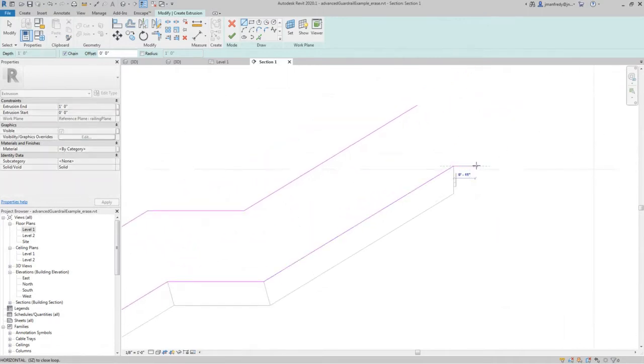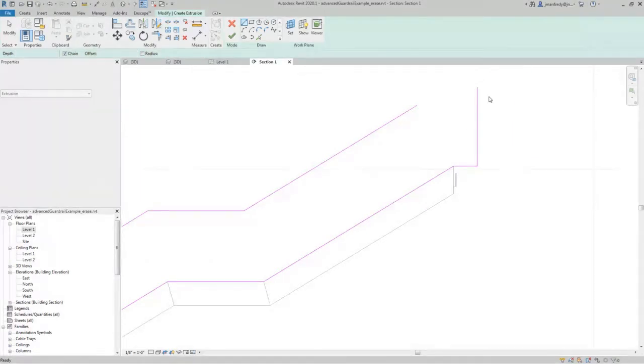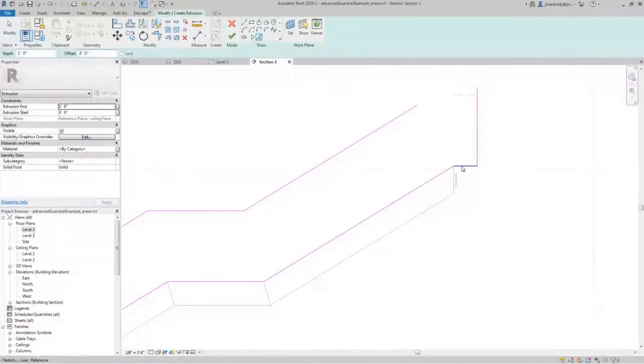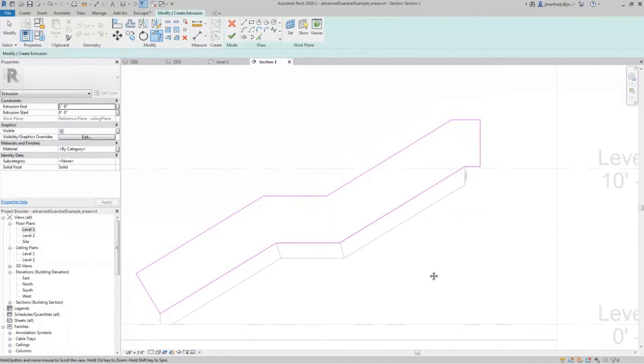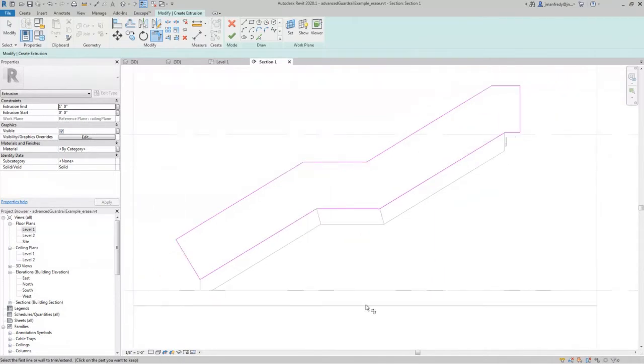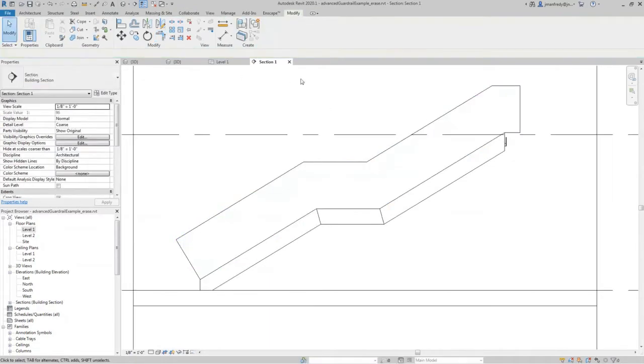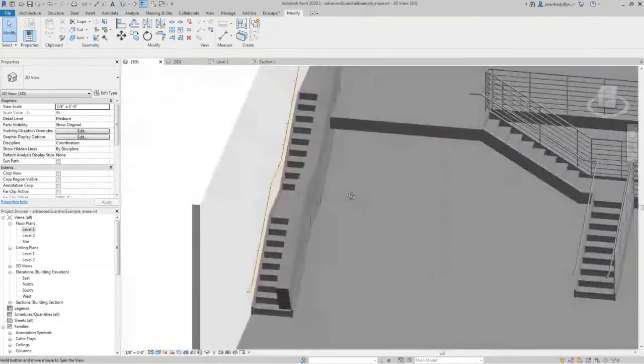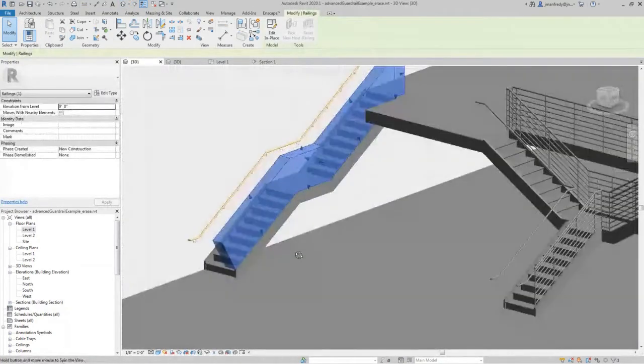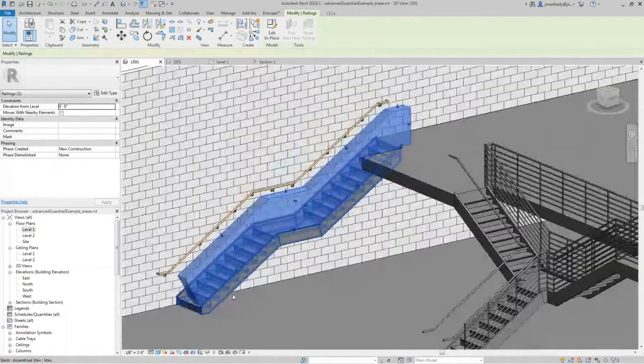And maybe the top one is going to go this way and up, and perhaps I offset it 3 feet as well, whatever dimension you're after. And I trim these pieces. So there, I want the railing to follow this shape, but it's a wall. So when I accept it, and I accept it here, I've built a 3D model right there of a wall. And what I'll do is I'll use this wall to trace my railing as a guide. And then I'll add the vertical members and other pieces and parts of this model as I go.